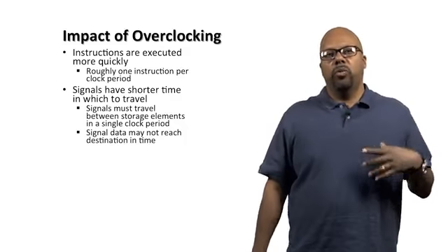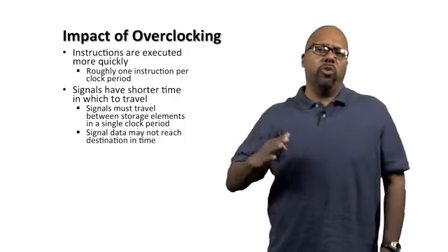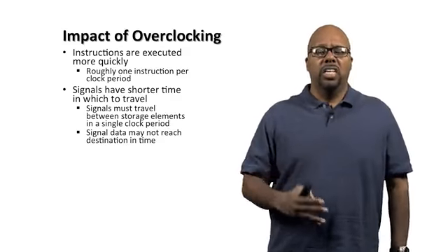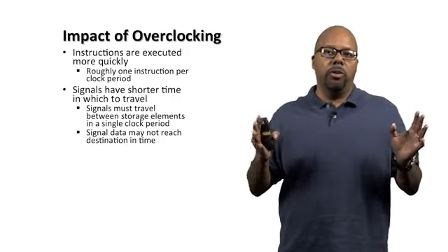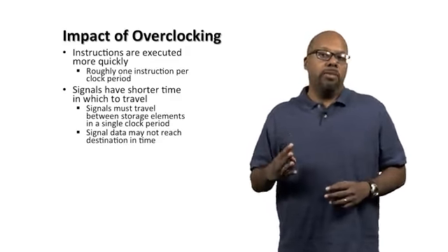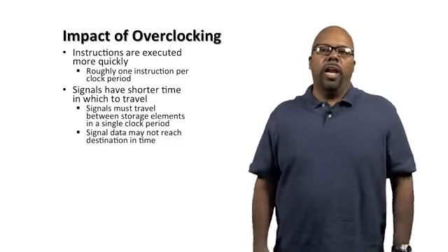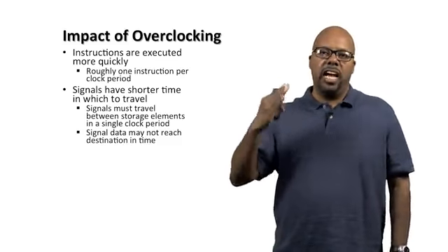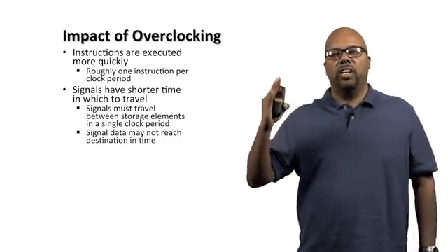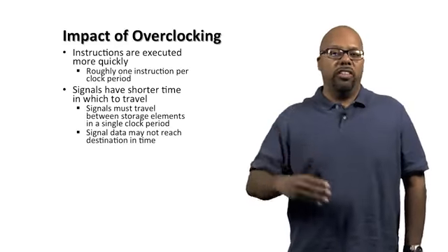And remember that when they fabricate these chips, often the chips are fabricated to a higher frequency than what they're sold at. So for instance, I'm making up numbers a little bit, but let's take our processor. It's sold at 900 megahertz. So maybe it was designed for 1 gigahertz. But what happened was during testing, they tested at higher and higher speeds, and eventually they said, oh, wait a minute, once we get to 1 gigahertz, it crashes, right? So we're going to cut off 10%, bring it down to 900 megahertz, and sell it at that.